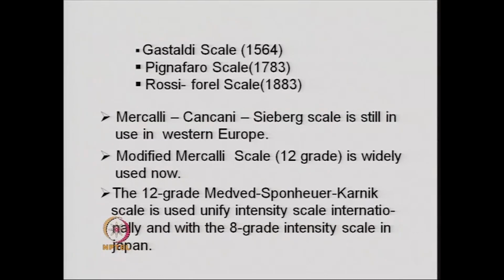The Mercalli-Cancani-Sieberg scale is still in use in Western Europe. This is again one of the oldest scales. The modified Mercalli scale in 12 grade is widely used now. The 12 grade Medvedev-Sponheuer-Karnik scale is used to unify the intensity scale internationally, and with the 8 grade intensity scale in Japan.